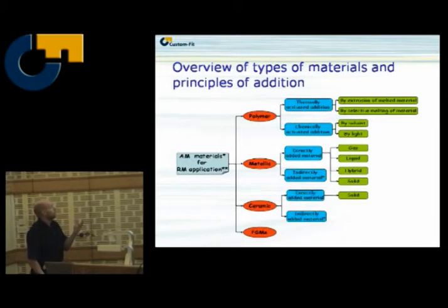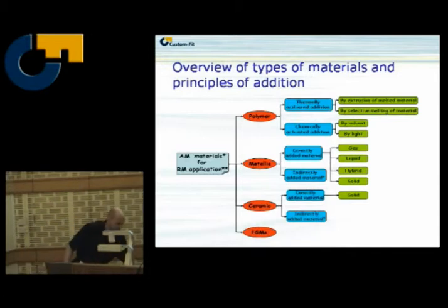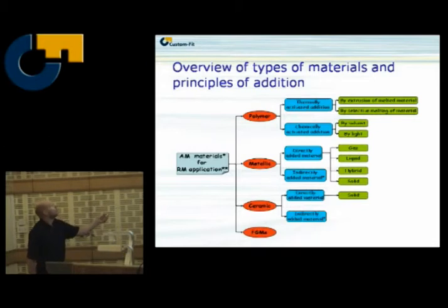If you take an overlook, materials can be added in different ways, like polymers up there. You can activate the addition thermally by just heating it together. That could also be done by extrusion, melting material, selective melting of the material, or you can activate the addition chemically, either by solvent or by light exposure.